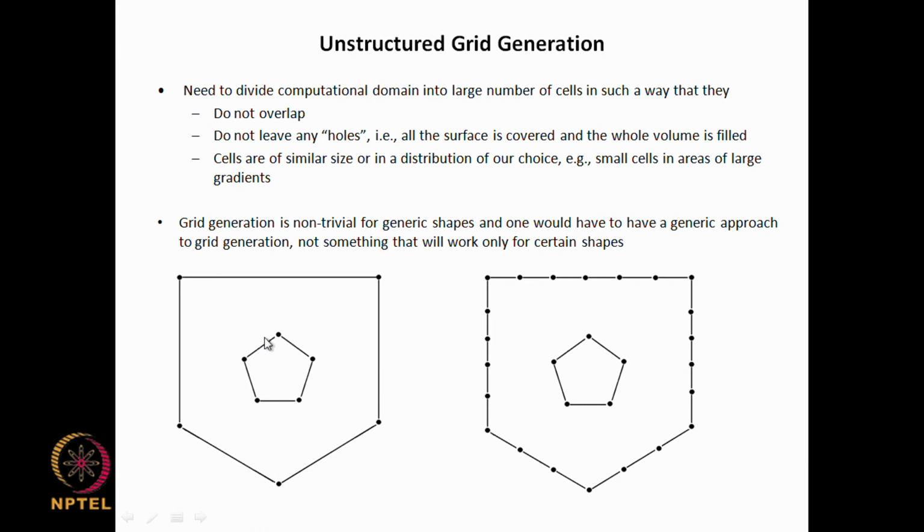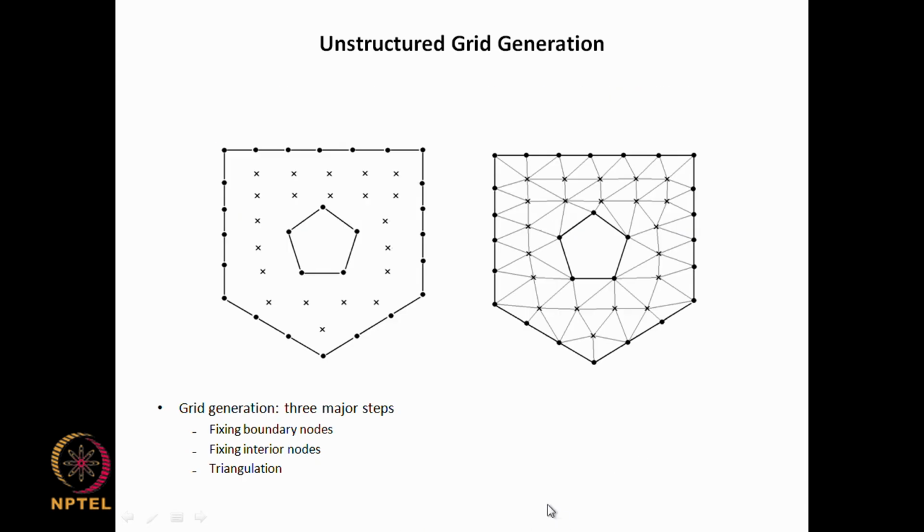Given the fact that we have a domain which does not fit into a regular constant x, constant y kind of thing, as shown here for this simple case, and given that there may not be any regularity, you need to have some imaginative way of trying to put interior points throughout the domain in such a way that they are separated roughly by a desirable distance apart, and that they are there everywhere and only inside the computational domain and not external.